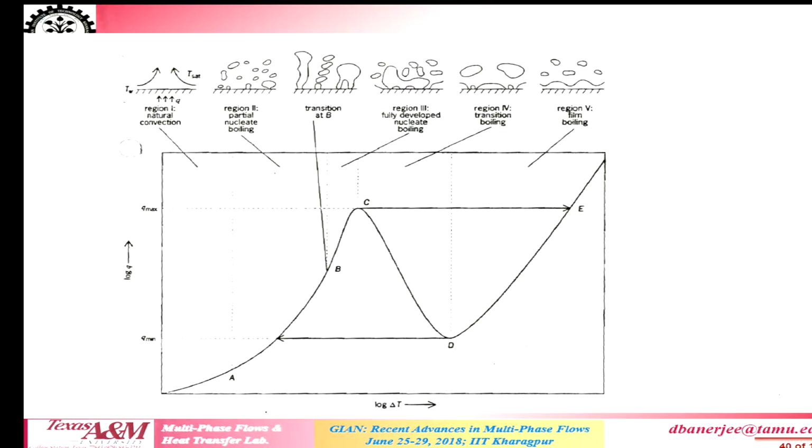And because there is a variation in your heat transfer, the temperature on the surface of the heater changes. Now the weird thing is, when the surface temperature of this heater changes, you cannot measure it, because typically your thermocouples are about a couple of millimeters below the surface, and so all those temperature oscillations occurring right on the surface of the heater damp down by the time they reach the thermocouple, number one.